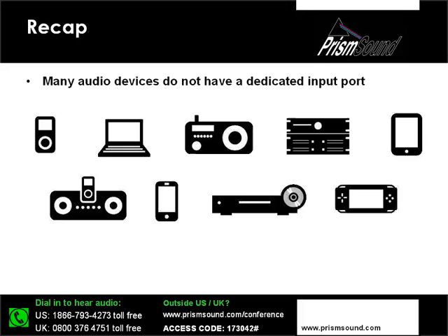So let's just recap what we have covered today then. First of all, we saw that there are many audio devices that do not have a dedicated audio input port, and that presents us with a particular challenge when it comes to analysing the performance of these devices. We can't use closed loop testing, we cannot connect our signal generator to the input of these devices, and therefore we are condemned to using test files for the purposes of measurement.